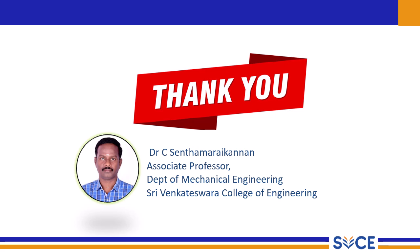Next, we defined a transducer as a device that transforms physical variables into electrical signals, and then delved deeper into variable resistance transducers using the strain gauge as a primary example, and how the Wheatstone bridge is used to convert the strain into an electrical signal.